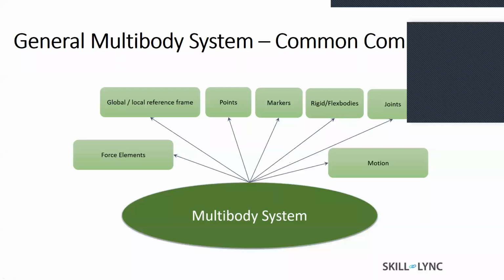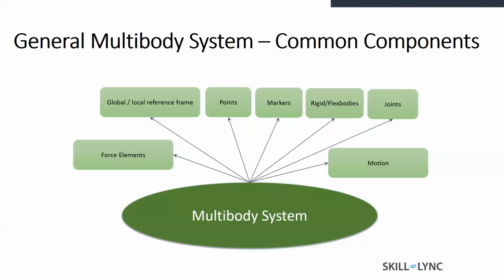Yes. For example, if you talk about engine dynamics and you're dealing with NVH, think that you're trying to get the vibration at the various engine mounts. You'll have to run the same code every day, or whenever you want to do the analysis, you need to run the same script to get the answer. Instead of that, you can write one script which, if you just change the model name, will be able to do the analysis for that too. You don't have to write the script again and again, or run the same analysis for different models. There should be a master script to which different model files can be attached, and you just get the results. That's what I mean by automation.